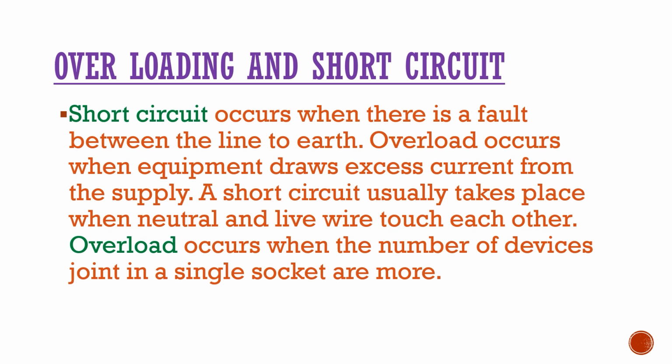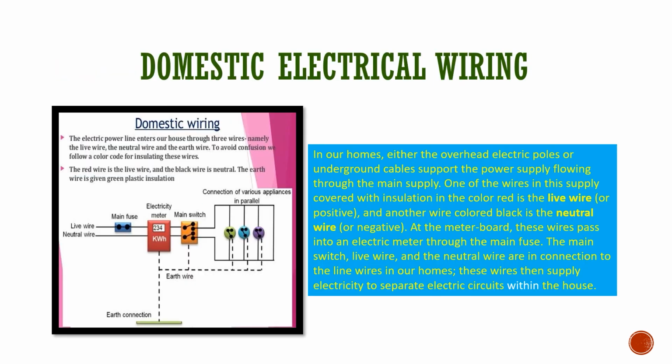Okay, next you will learn about the color of the wires. You will see in the domestic purposes, whatever the wires we use, you will see three types of color. As per new international convention, the live wire should be brown, and neutral and earth wire. Neutral will be light blue and earth wire will be green or yellow. Green is earth, green is the earthing wire.